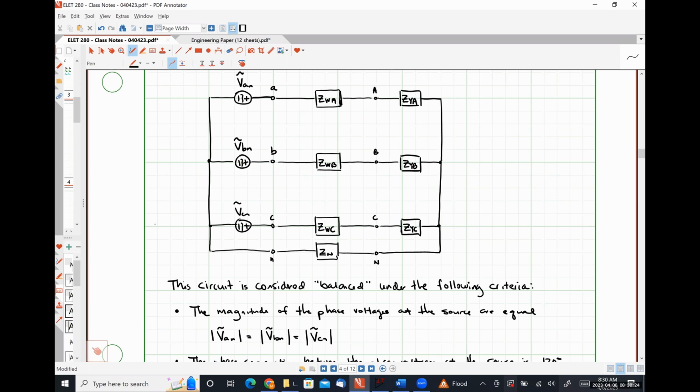So even if you're dealing with an unbalanced impedance, because that's what you were given, if you get to implement multiple ones of them, you can balance things out by swapping the phases on the single phase portion of that load. It's a very, very common practice. You get to physically go out there and wire it.